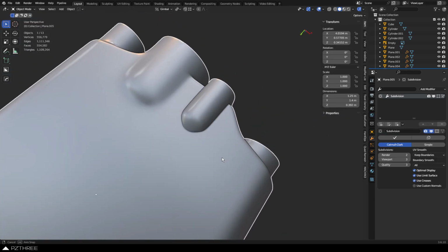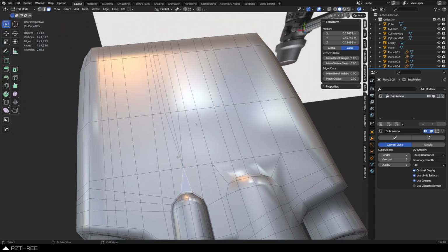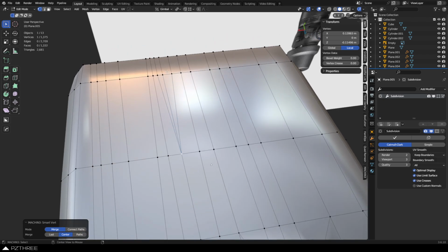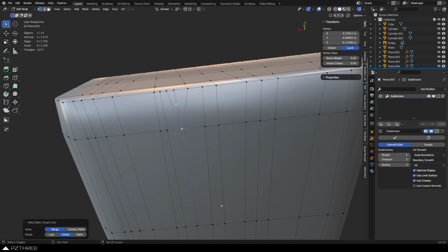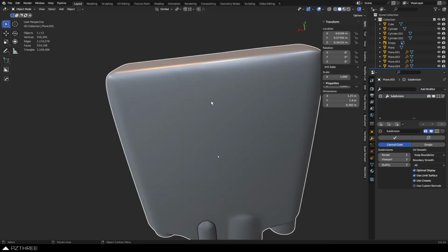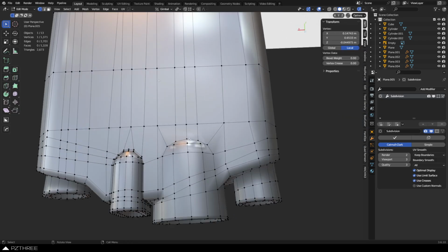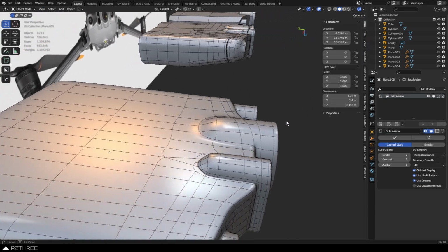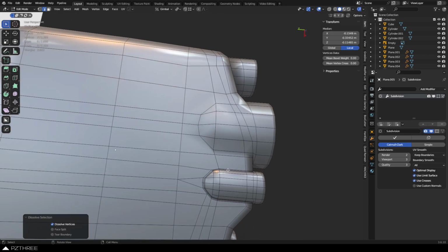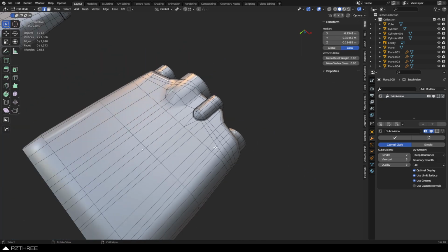If it's a flat surface, you know, it's not a big deal. Creates a quad, not a triangle. It's just going to have a pole in it though. So you can see like that whole section there is starting to work out basically, right? Start doing things like that if needed. Also, this will influence your unwraps. So if you're going to UV unwrap, you know, some things like that can come into play. You can see like that whole section there, you can maybe just reduce it, use the triangles. Yeah. Rather cool stuff you can do with these models.